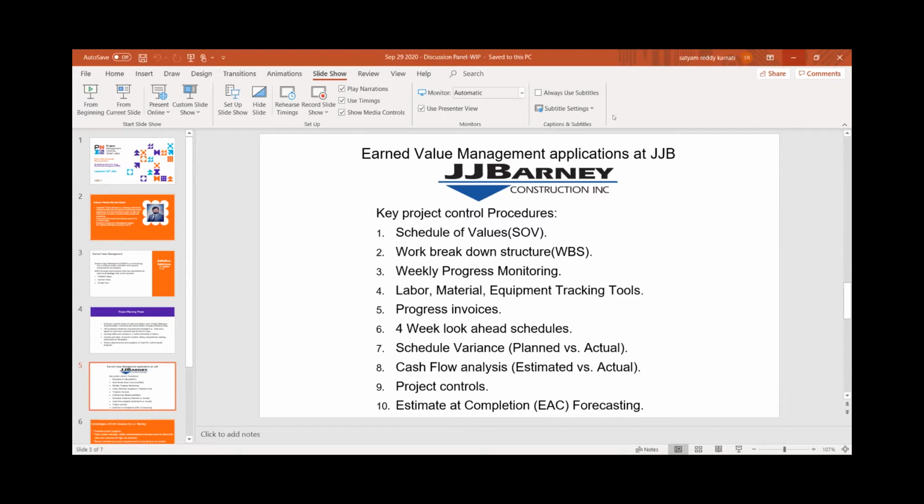How many total linear feet of exterior grade beams do I have, and the interior? The percentage I have here is based on the width and depth, and then I distribute the cost accordingly. That's how I come up with the earned value in this column. I have finished 24% till date on this, and I have earned 50,976.